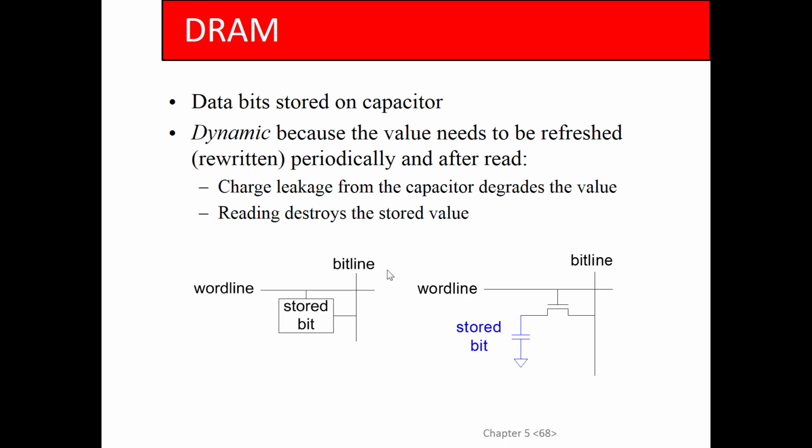But it can't be done. There's no way to do it. You can put logic in a DRAM chip, but it would be unusably slow because of the capacitance. And likewise, you cannot put DRAM onto a CMOS chip, because it wouldn't have enough capacitance to work. It would have to be refreshed so often that it would be unusable. So anyway, that's the story with DRAM.